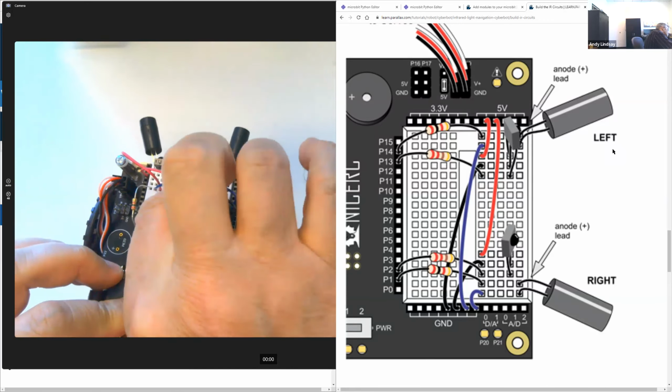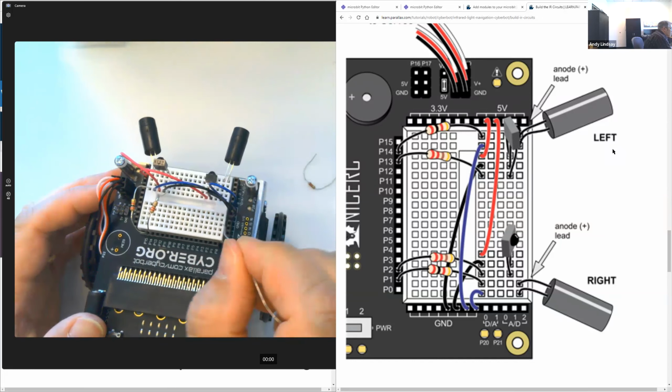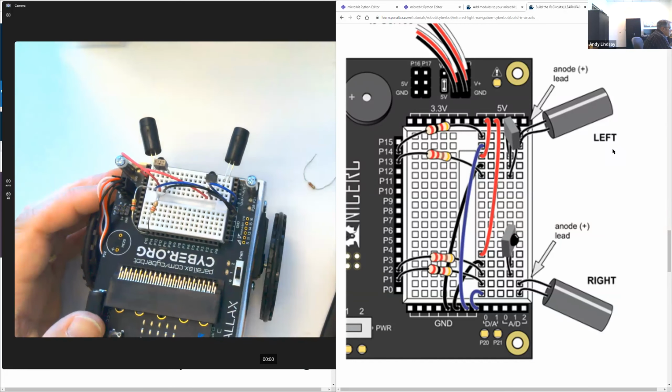Another question, can you short circuit the breadboard? Yes, if you insert a lead unusually far into the socket, it might be snaking around and connecting itself to other parts of the breadboard and inadvertently connecting 2 rows of 5 together.